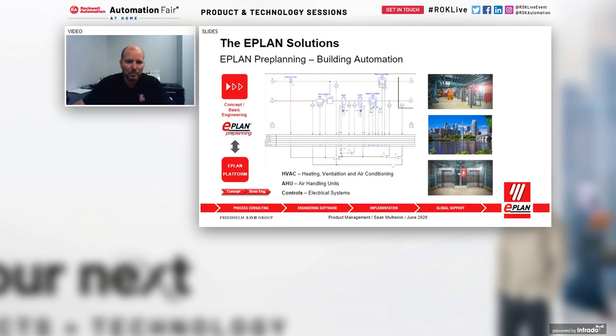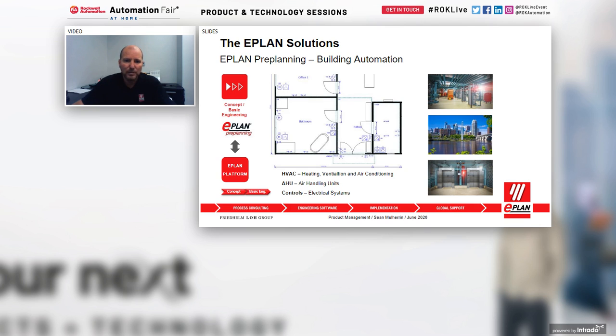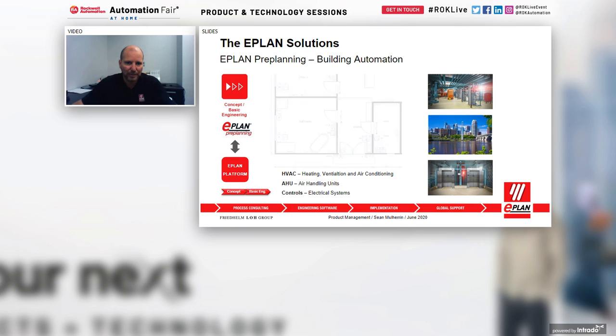Important is to capture the number of signals available and to make sure that these signals are all wired and controlled by your control system in the building. Here you also have overlays on top of existing architectural drawings. So you could import from Revit, for example, an overview of your building. And on top of that, you could start capturing all of your control system, whether it's for security system, alarm systems, your lighting system, your electrical control systems of that particular building could be done on top of an overlay that you would import into pre-planning.